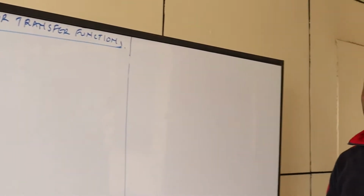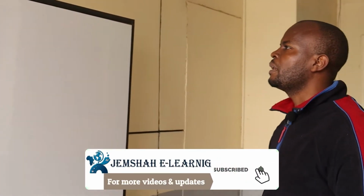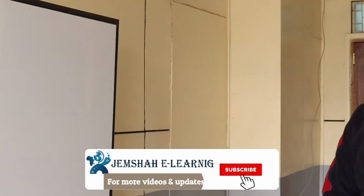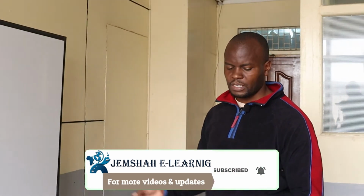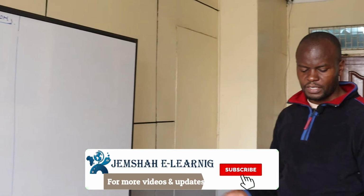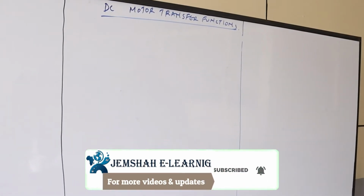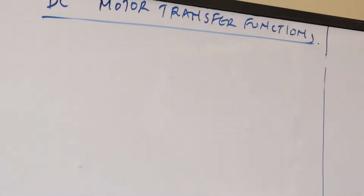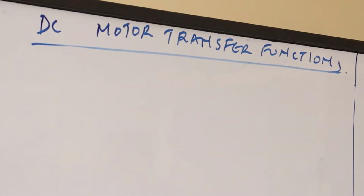So we are going to wrap up the transfer function and system modeling by looking at the DC motor transfer functions. DC motors are often employed in a control system where an appreciable amount of shaft power is required. They usually have separately excited fields, and they can either be armature controlled or field controlled.